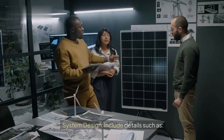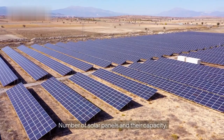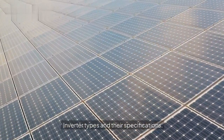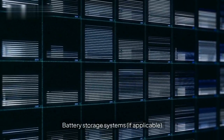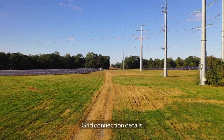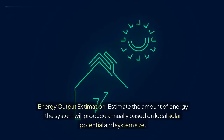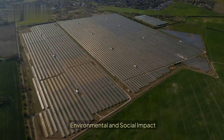System design. Include details such as number of solar panels and their capacity. Inverter types and their specifications. Battery storage systems, if applicable. Grid connection details. Energy output estimation. Estimate the amount of energy the system will produce annually based on local solar potential and system size.